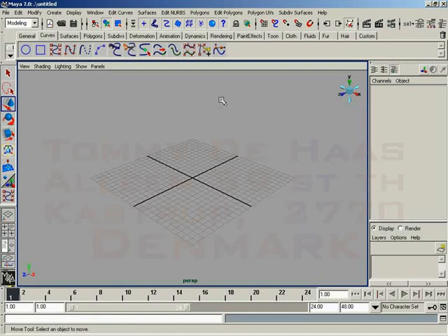The Trim Surfaces tool is a way for you to use a curve-on surface to hide away a part of a NURBS surface. It's kind of like a Boolean operation, except that it's not really removing any geometry. Let me give you a quick example.